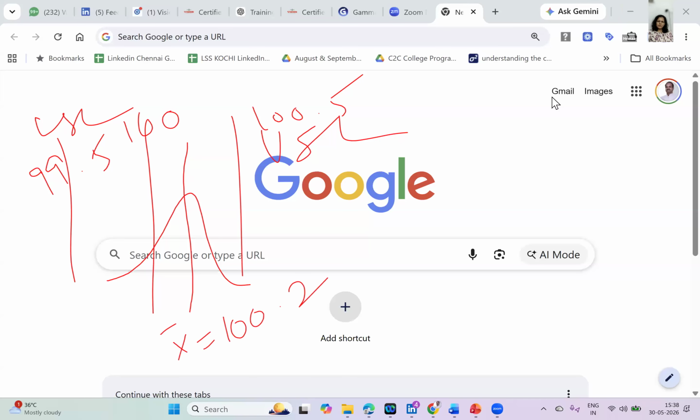Process is shifted right side. You see here, the shifting is towards right. It is moving towards the right side wall, isn't it? The process is shifting towards right. If the process is shifting towards right, then CPK will be equal to what? CP upper. Very good. CP upper. You don't even have to calculate CP lower in this case, right? You only have to calculate CP upper.